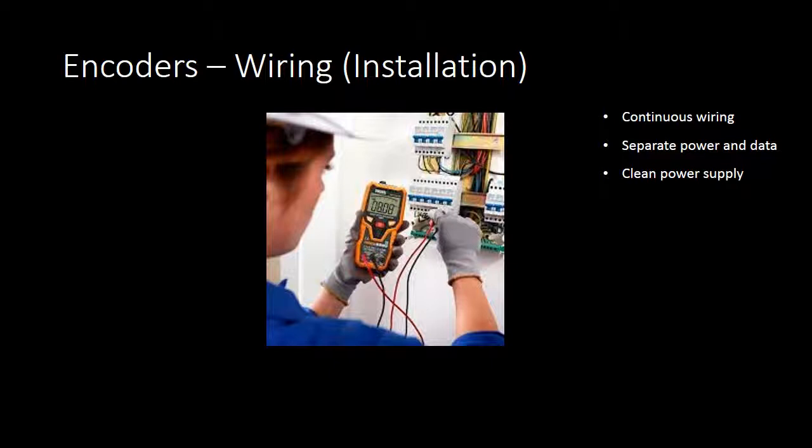Some encoders have provisions for a case ground connection through the connector or cable if a ground cannot be secured through the mounting bracket or machine ground. Use high-quality shielded wire and connect the shield only at the instrument end. Also, an encoder using twisted pair shielded cable ensures that wire-induced currents will self-cancel.